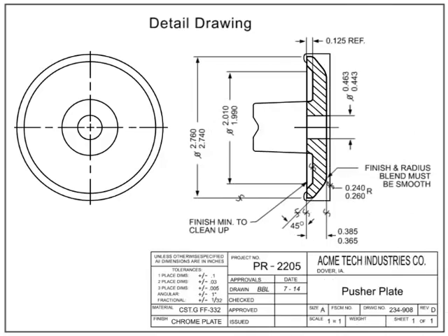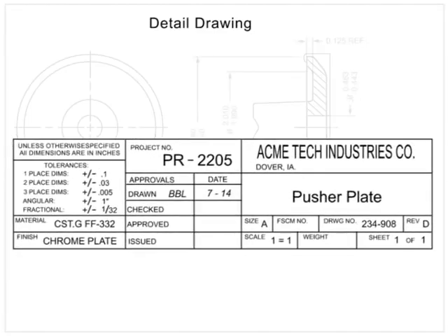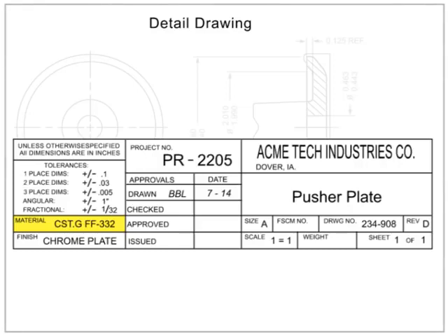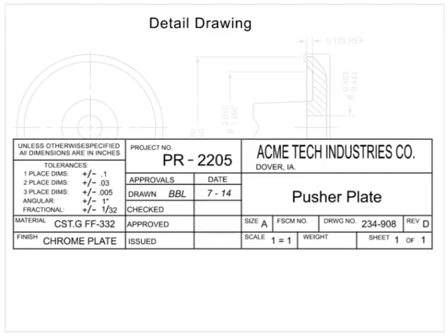Machine drawings are detail drawings that require machining to create the end product. They can be developed using a cast part as the original material. In this drawing, the casting from the last example was used as the starting material. This machining drawing will remove material from the original casting and add the finishes required to produce a final product with its own unique part number. Only the dimensions necessary to convert the original cast part into the new part are required. The casting dimensions are not shown.